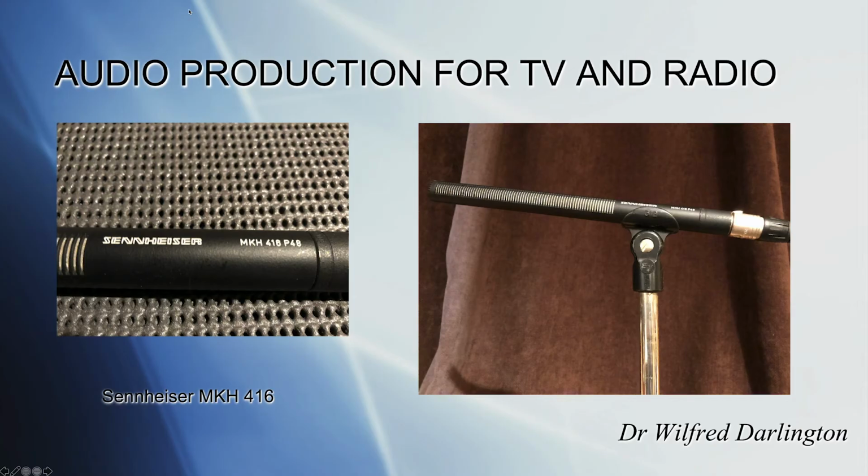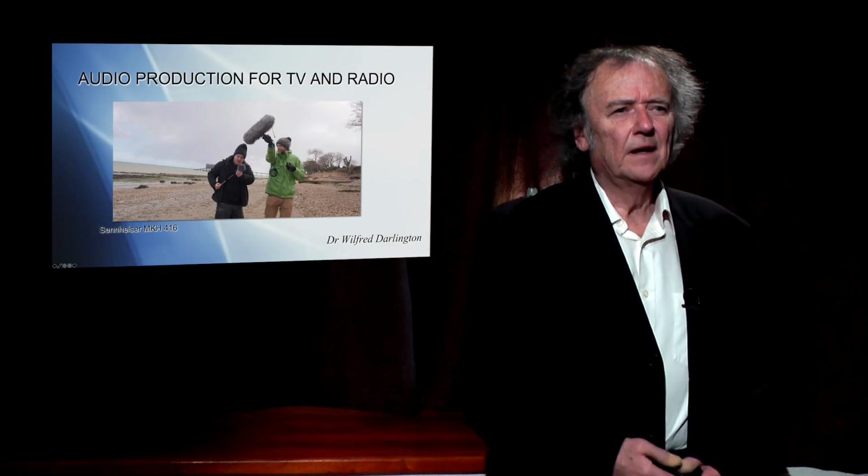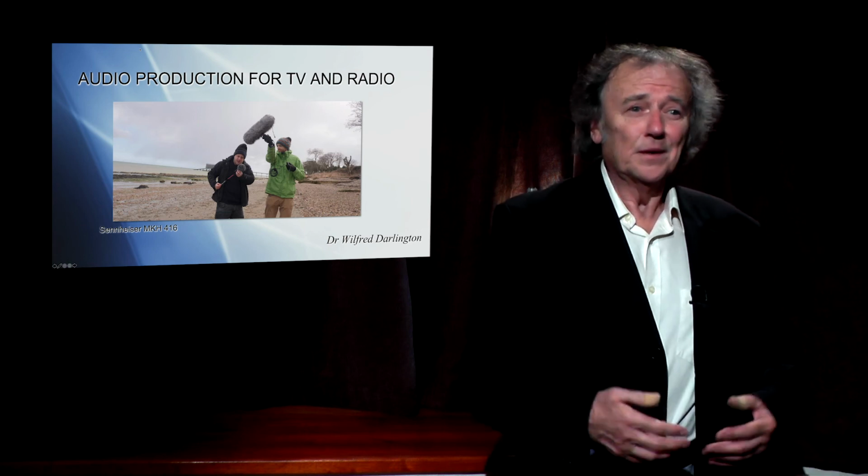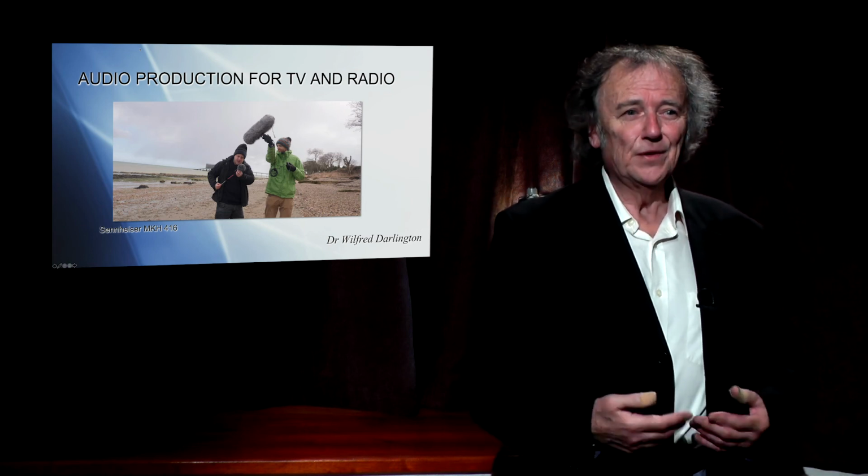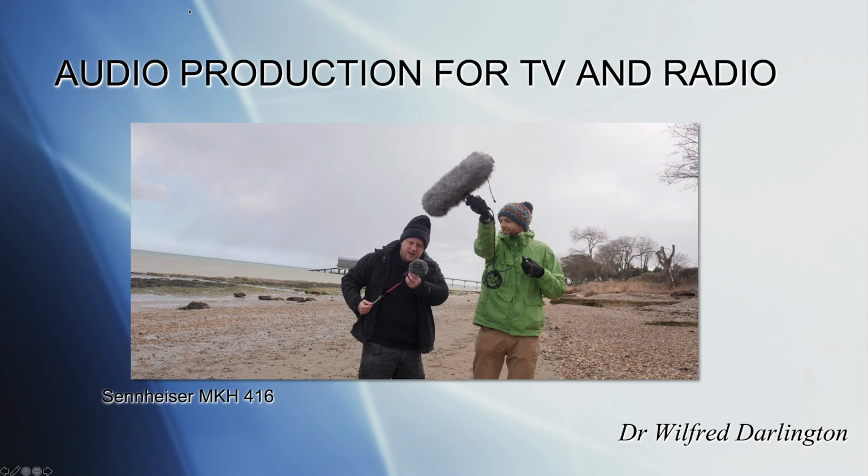This leakage causes bumps and crackles in the audio output. But with the RF system, this doesn't happen because there is no direct voltage on the capsule and therefore no noisy leakage. So, if you are working in high levels of humidity, an MKH will keep you out of trouble.